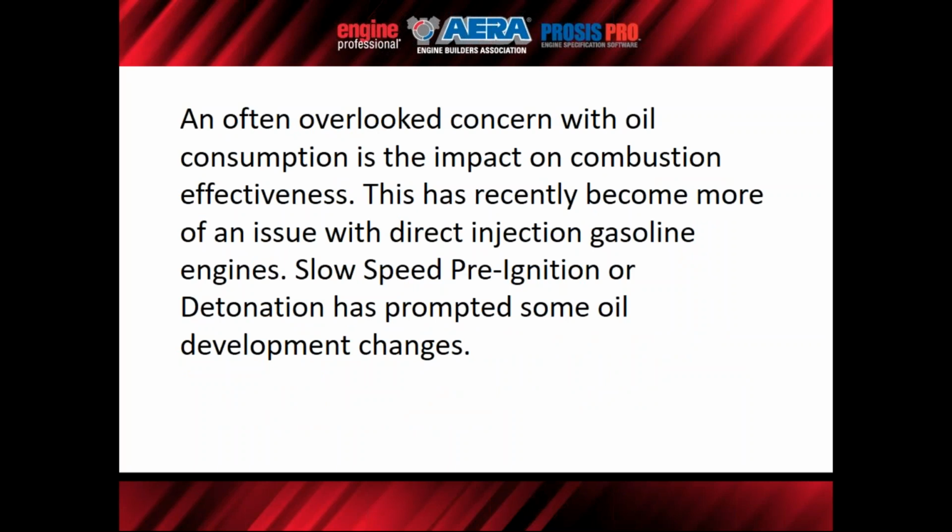And this is something that's actually being talked about a bit more now, not necessarily because of valve stem seals, but the direct injected gas engines. Since they don't have the fuel atomization in the intake runner, they're not washing the oil down. There's less time for the fuel air atomization now, since it's being injected directly into the combustion chamber.